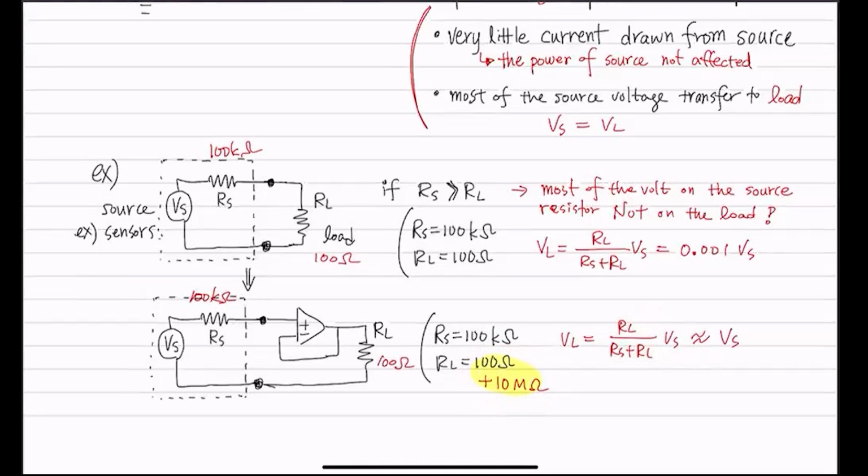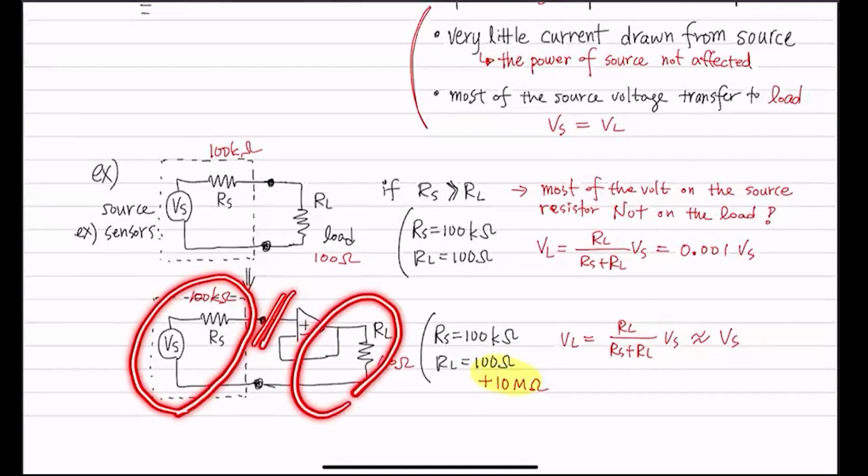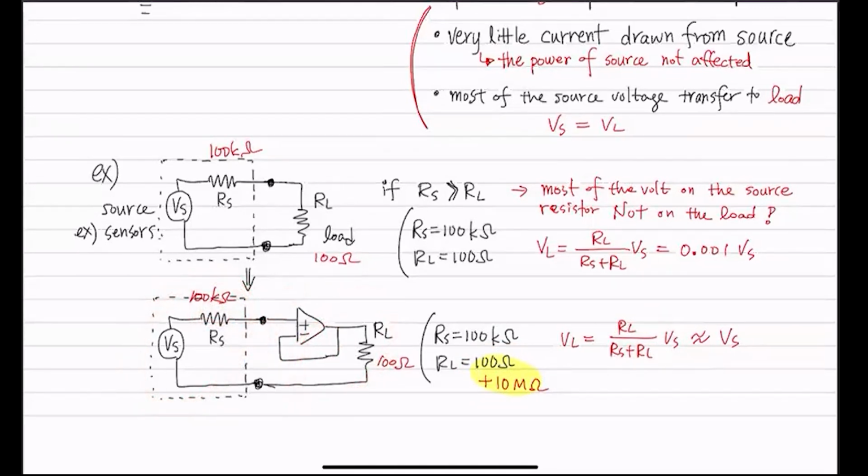That's the reason why sometimes you want to have a voltage follower in between some sources. It's kind of blocking the energy consumption, qualitatively speaking. So instead of burning all your energy at this parasitic resistor, it is passing that information to your load where you are actually measuring.